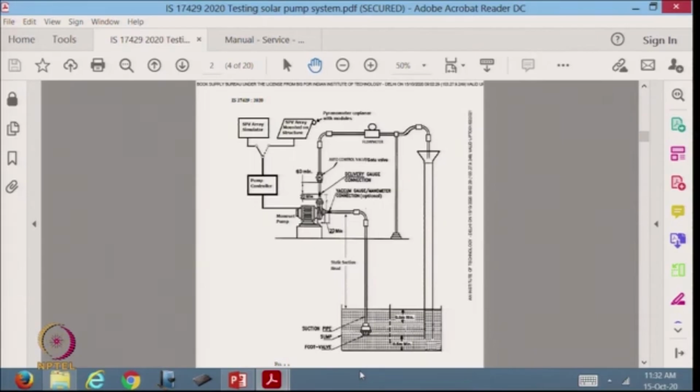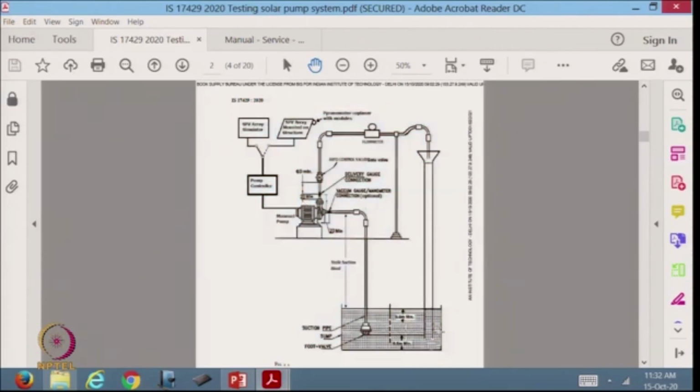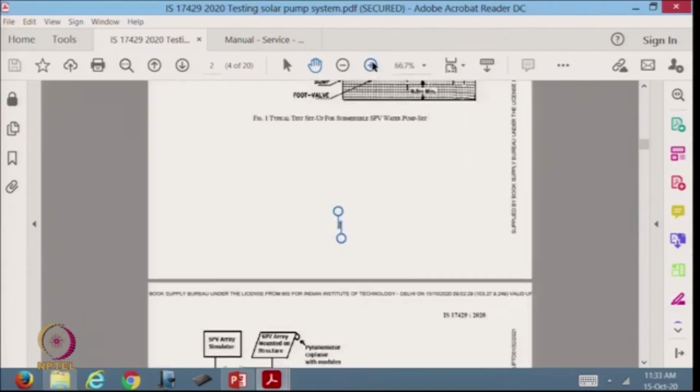So, this sketch is like a concept design of an experiment, slightly more than that, because some information is given here, like what should be this diameter, what is this distance, what is this distance here, like that. And it is from here that we do the detailed engineering and say what is the length of this pipe that I should buy, what is the type of threaded connection I should have, how do I make this leak proof, what is the type of mounting that I need. All of that is the detailed engineering design of the setup. But this is something which is common to all experiments.